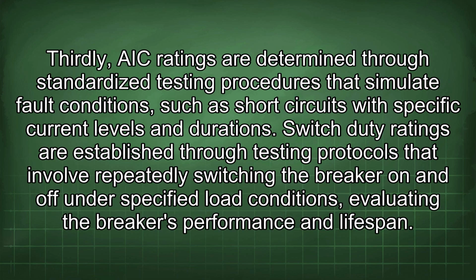Thirdly, AIC ratings are determined through standardized testing procedures that simulate fault conditions, such as short circuits with specific current levels and durations. Switch duty ratings are established through testing protocols that involve repeatedly switching the breaker on and off under specified load conditions, evaluating the breaker's performance and lifespan.